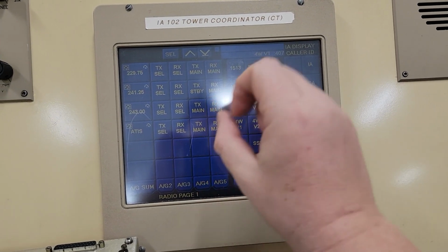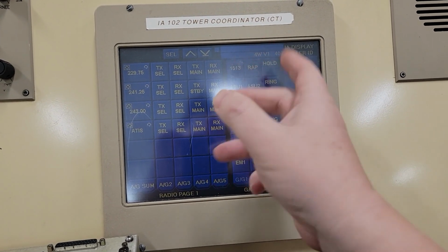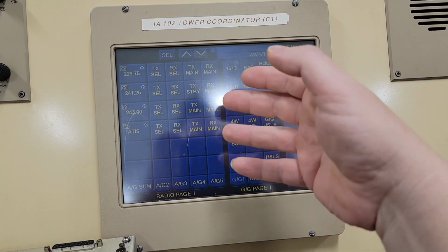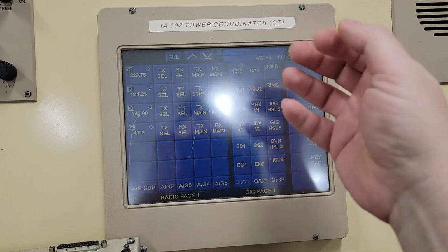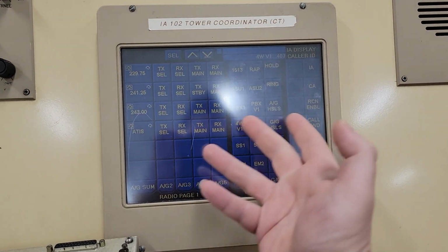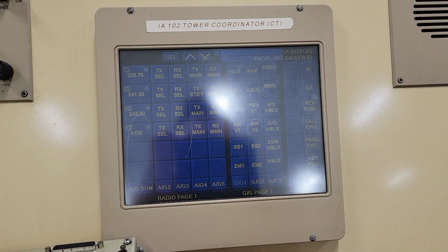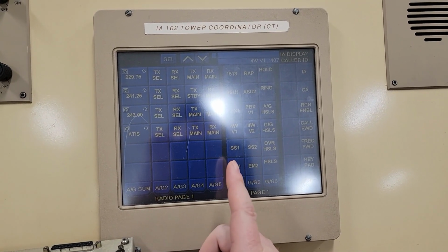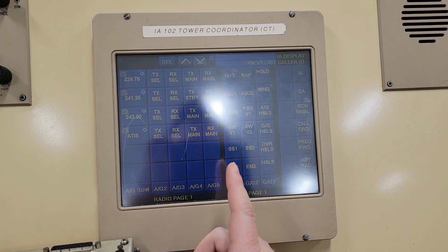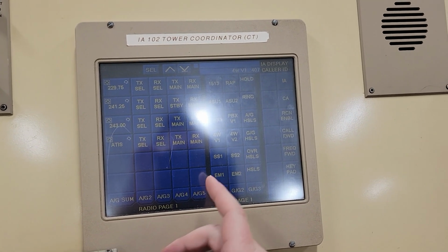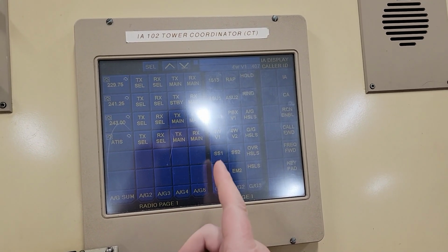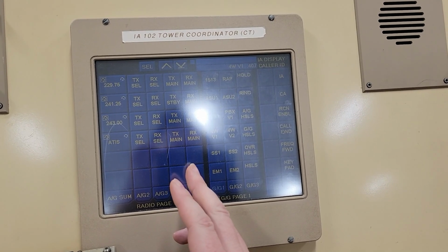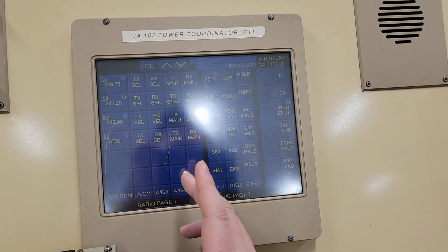Now the display itself is only 480p. If you were to look at the signals and everything, you'd be able to determine the lines. You'd be able to determine that this is essentially a 480p display unit. And then again, the horizontal and vertical sync. The horizontal sync, if I'm not mistaken, I typically get these backwards. If I do, I'll correct myself later on. 15 kilohertz on our horizontal sync, and then 48 hertz on our vertical sync. As a matter of fact, in a few minutes we'll see that itself.